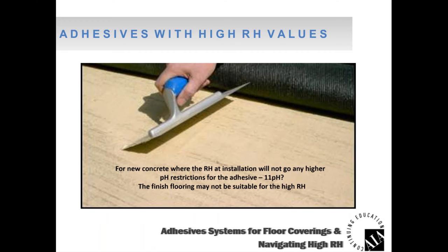So that moisture can go through the adhesive and potentially affect the floor covering. And if that floor covering is only rated at 80 RH, then you've got a failure with the floor covering, and you're in trouble. The adhesive manufacturer says, hey, our product isn't affected, it's the flooring. And then the flooring manufacturer says, hey, your RH is way higher than our maximum. So ask the question, that's all I'm saying. Make sure you're on the same page with manufacturer's recommendations.